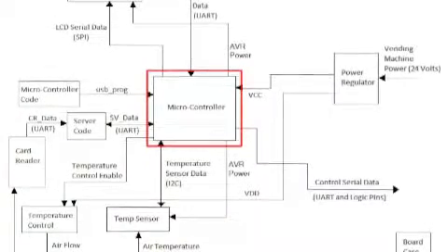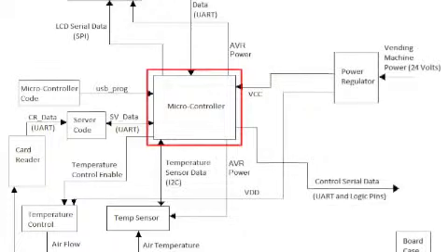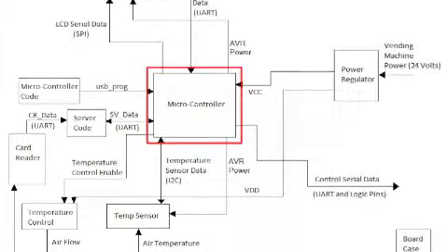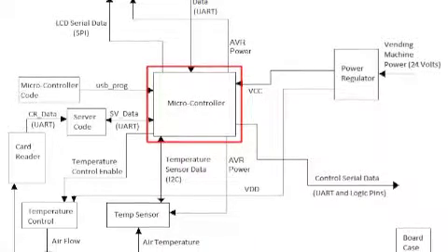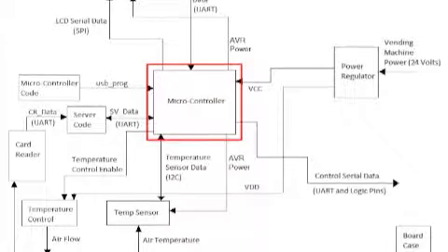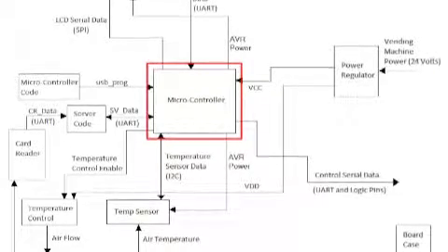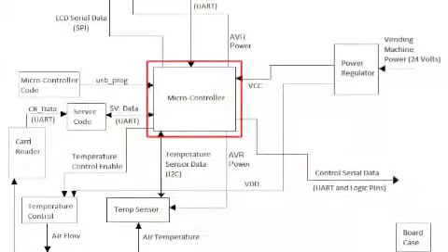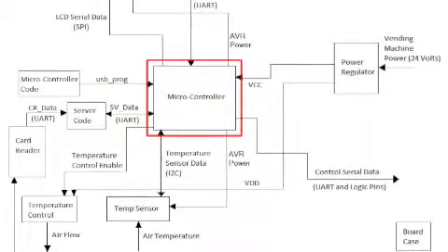The microcontroller is used to control every peripheral device in our design. It utilizes SPI to talk to the LCD, utilizes UART to talk to the server and the CoinMech, it utilizes USB to talk to the programming computer, and then several logic pins to control the vending machine and the bill mech. It also utilizes I2C to talk to a temperature sensor.